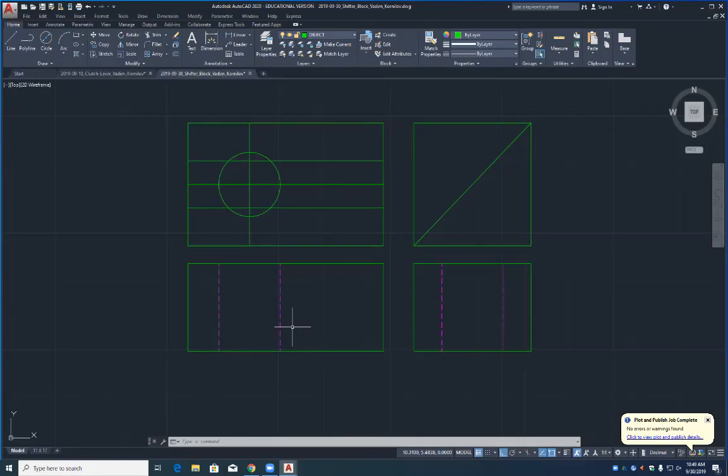That 1 inch is what the width of that slot has to be measured on, and it can vary a little bit according to the tolerance. So it could be 0.995 or 1.005, anywhere in between there. That's what it's telling us, because we're just doing plus or minus 5 thousandths.